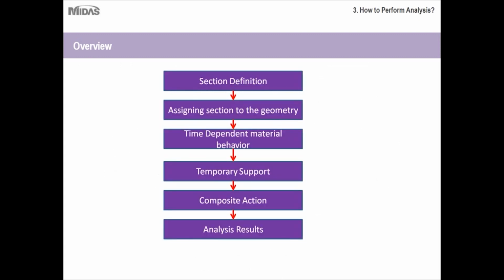And this is the layout for the demo that I'll be going through today. So I'll start with the section definition and then assign that section to the geometry of the bridge. Then I'll be defining the time-dependent material behavior for this particular bridge.